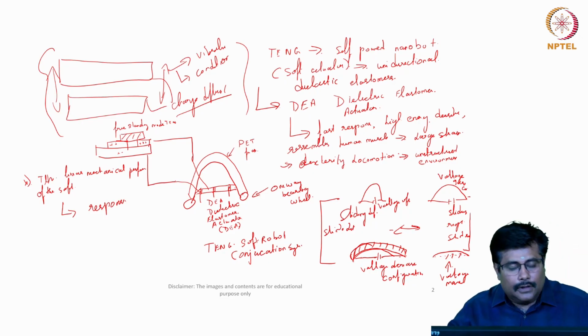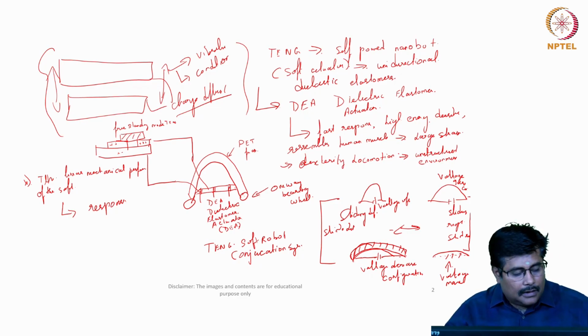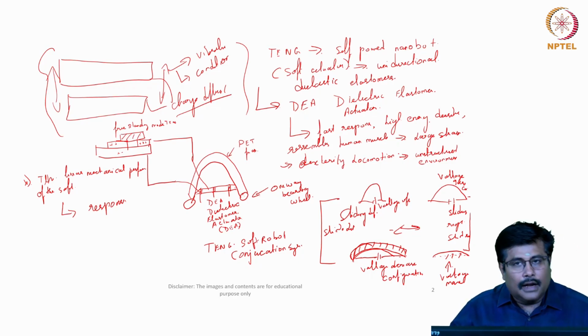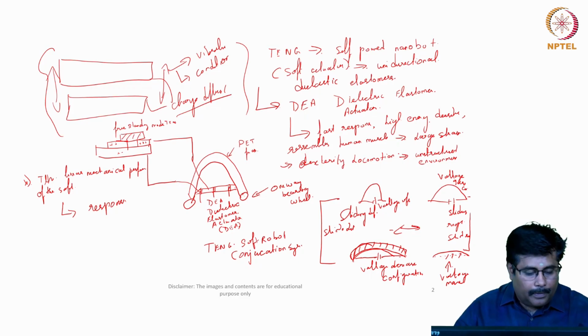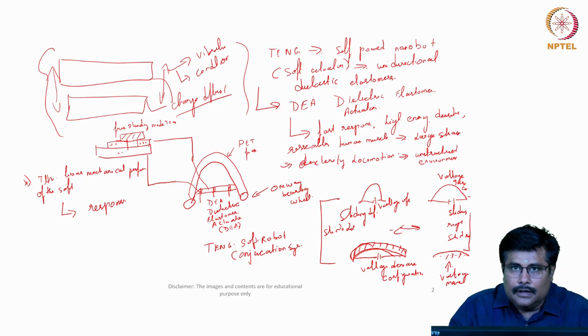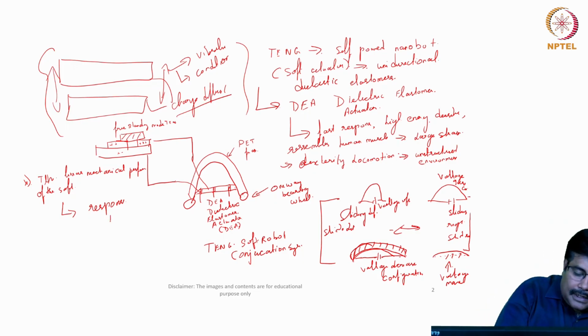Once we look into the response time of these structures, it plays a vital role with reference to the usage of this system for different conditions. Now in that aspect, if we look into the performance of these unidirectional DEA driven soft robotic structures, it aligns the direction of DEA in extension with the robotic motion to achieve high energy efficiency conversion.